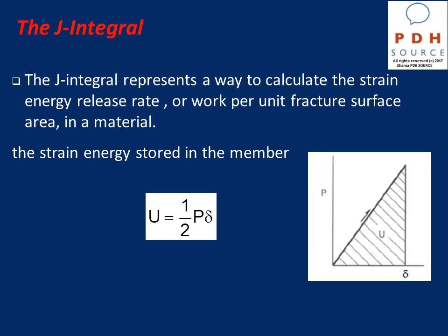And if we assume that we are working in the linear phase of behavior of the material, then U, which is the strain energy, is going to be equal to 0.5 multiplied by P multiplied by delta, where P is the applied load and delta is the deformation of the member.